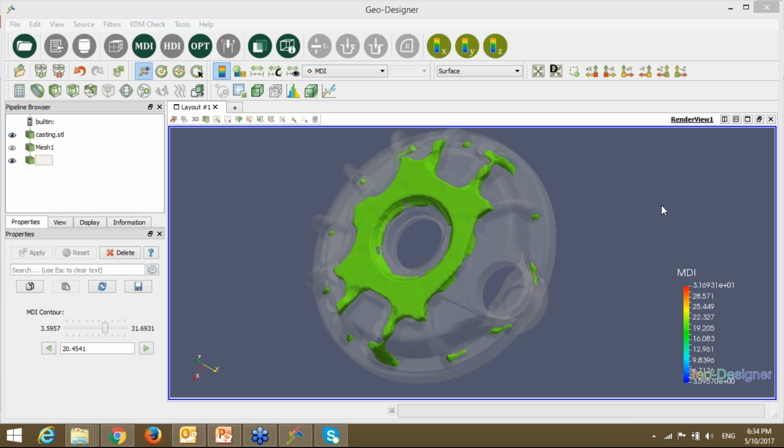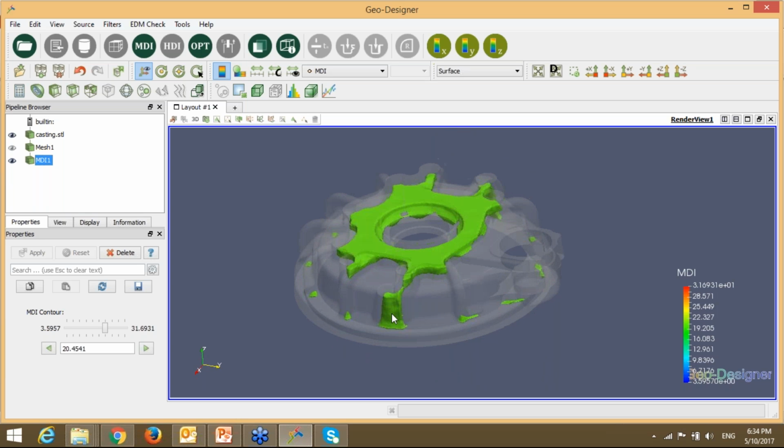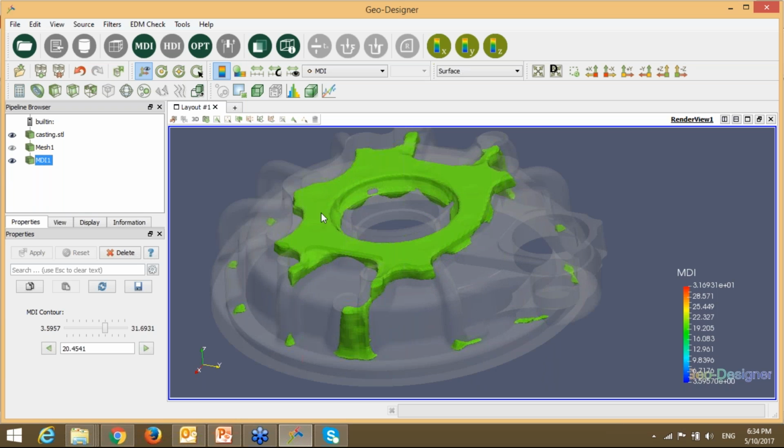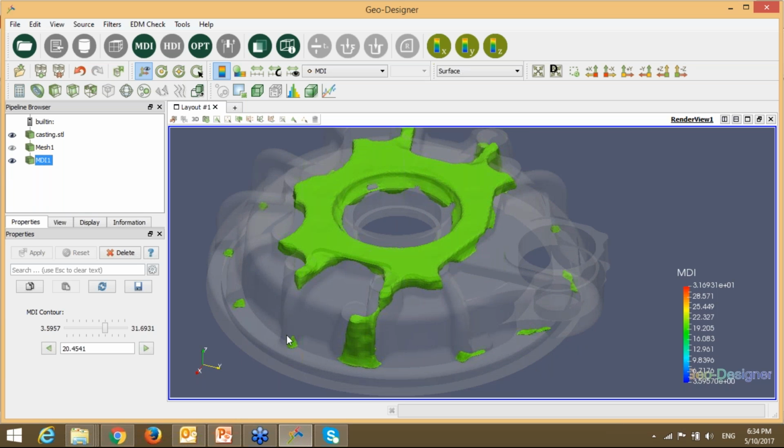Another thing is how we decide the point required for a chill or riser, or whether just hot metal through the ingate is enough. No, this is specified from the size of the mass. What you see here is that if you see the mass available in the color here and compare it with this location, it is very high. That means this location on the top side will certainly require a riser or a sleeve. It cannot be addressed by just chills.